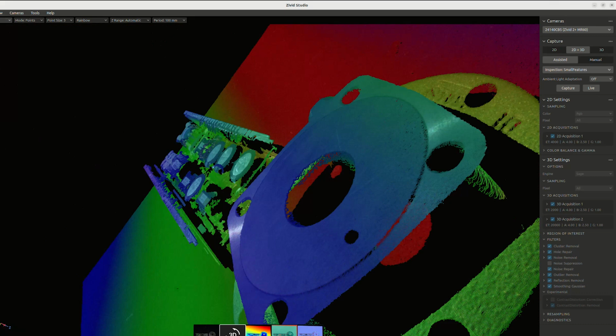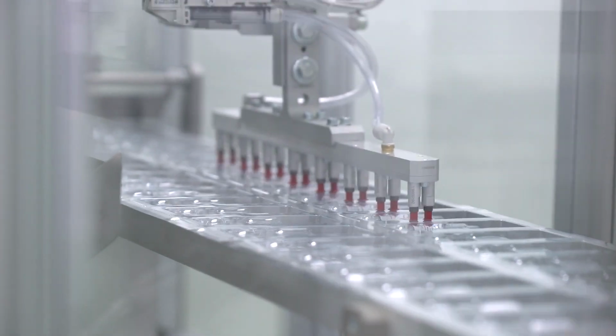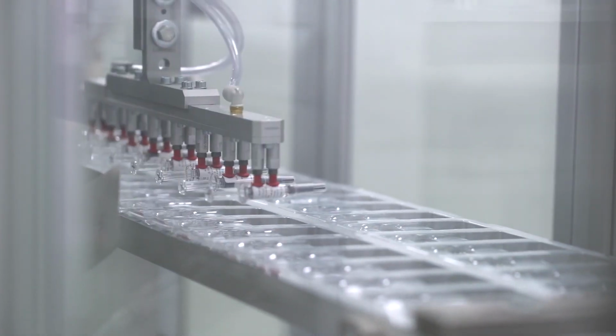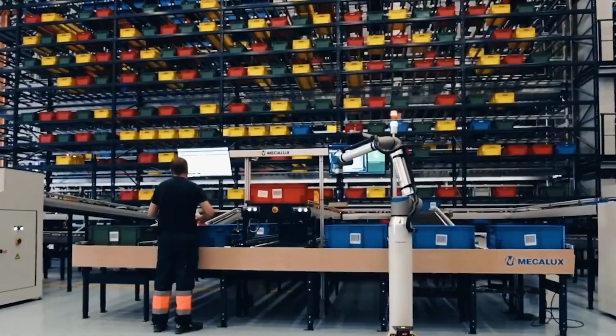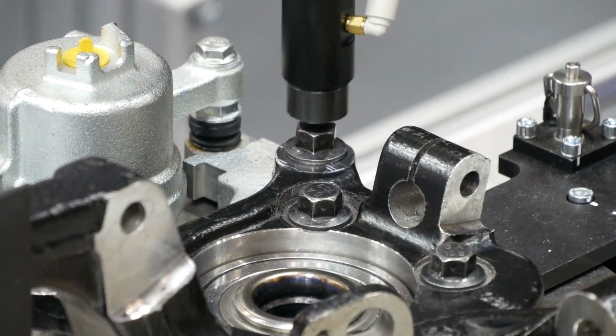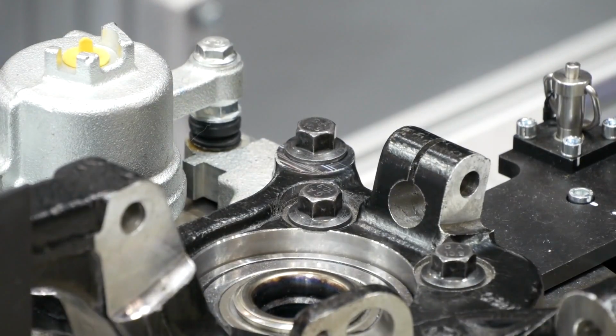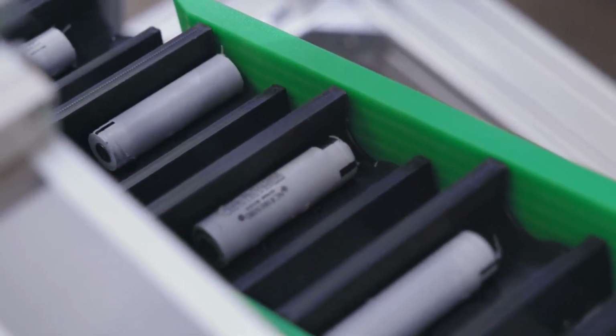But wait, one very important point as well. We want to care about, in warehouses, in factories, the ambient lights. In general, on average, approximately in terms of lux, we have 300 lux in warehouses and factories. That's what we can measure, and you don't really want to care about how you have to position the camera relative to the ambient lights, or if you'd like to add external covers to make more shadow into the scene.